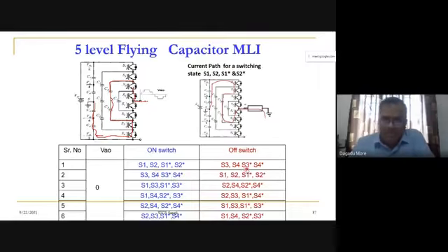We have to refer to the paper based on this, and find out how, with zero switching states, if you want a zero, we can choose which capacitor's voltage is not maintained constant, and whether you can maintain that voltage constant with appropriate selection of the switching state. So we have to find out new techniques for this. I will make the update and tell you, but papers are available, you can search on this, and it is possible just by switching state redundancy to maintain the balancing of the capacitor voltage.